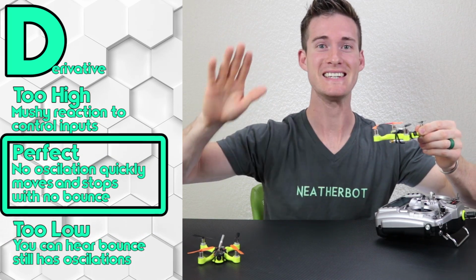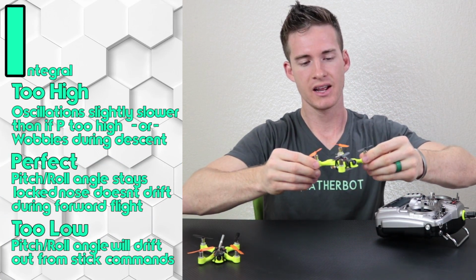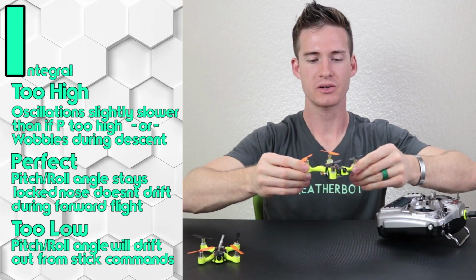Now that P and D are set, we're going to move to I. That's the middle position for the switch. The way that I like to do this is we increase I with this potentiometer on the side, and we continue to increase it.